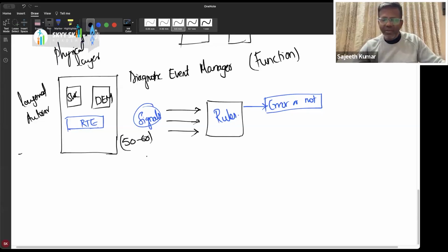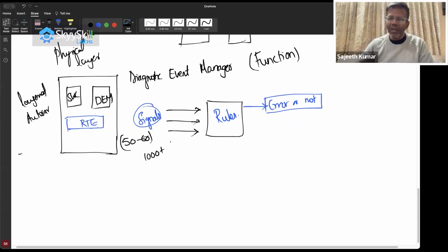If you take an IC engine vehicle, there are going to be 1,000-plus signals. Small electric vehicles, at least the ones which are not passenger vehicles, have fewer signals. But if you go for passenger vehicles, with ADAS and things like that, it goes to 1,000-plus, even 5,000-plus signals, because every single thing is being transmitted out over the CAN bus, right? So I just want you to have that in mind.